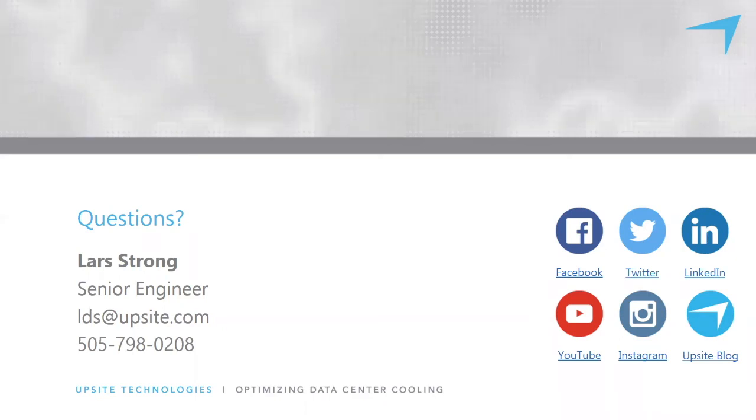That's a good point. And so there's a number of different levels of actually calculating PUE when you get into the detail. And one, call it the quick and dirty way, is to just take a look at the UPS output load. And that'll give you a ballpark number. But I appreciate Mauricio bringing up this point, because there are other losses. There's the distribution losses of the power through the cables after it leaves the UPS, and then there's potentially conversion losses in the RPPs that are in the room.